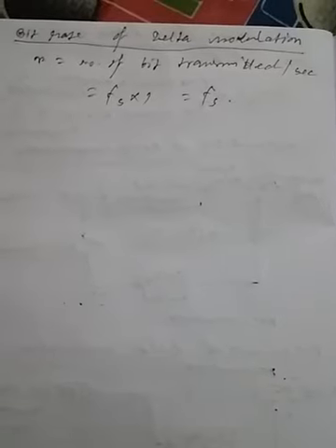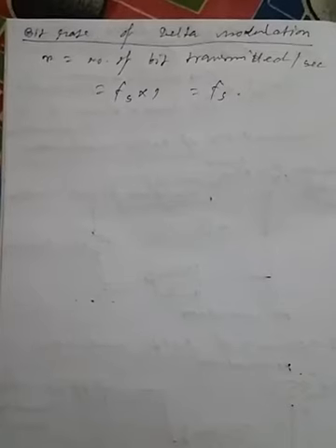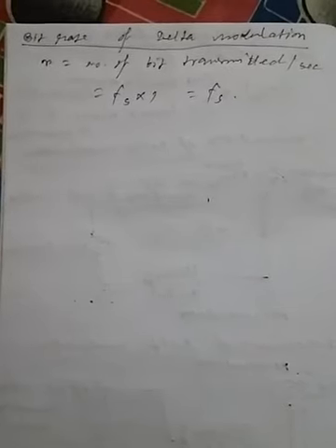To overcome the quantization errors due to slope overload and granular noise, the step size delta is made adaptive to variations in the input signal x(t). Particularly in the steep segment of the signal x(t), the step size is increased. Also, if the input is varying slowly, the step size is reduced. This method is known as adaptive delta modulation. Adaptive delta modulators can take continuous changes in step size or discrete changes in step size.